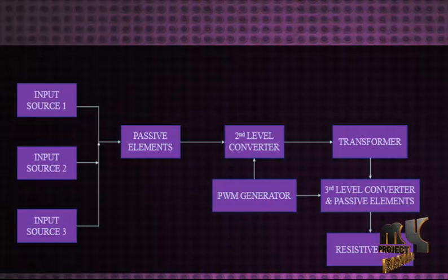The boost inductors connected to the input sources of different voltages are charged when S2 and S3 are turned on respectively. When the related switch S2 or S3 is turned off, the energy stored in the inductor is transferred to the load. The overall process has advantages such as high efficiency, constant output voltage, low switching stresses, multiple sources used and high conversion efficiency. So overall efficiency will increase.